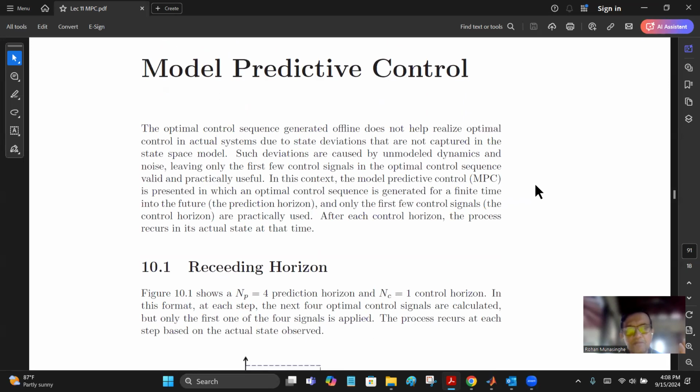So again, the highlight here is that in model predictive control, we stick to pretty much the same set of equations, but we change the controls to a feedback architecture from the feed forward architecture. The previous one is feed forward. You don't have any real time adjustments. But here, model predictive control has real time feedback based adjustments, and you also maintain the optimality. Okay, all right.